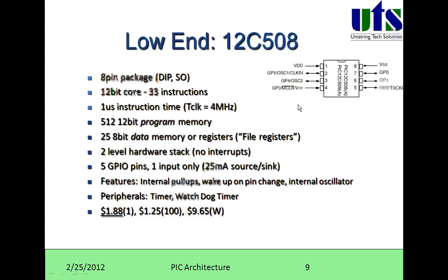And what are the features? Internal pull-up, wake up on pin change. Okay, that is if you are giving any signal to this one input pin, if you give some digital signal to this input, suppose one digital signal is present, if it is continuously positive, okay, high level, when suddenly it changes to low level, it detects it. Okay, that is a pin change, wake up on pin change.